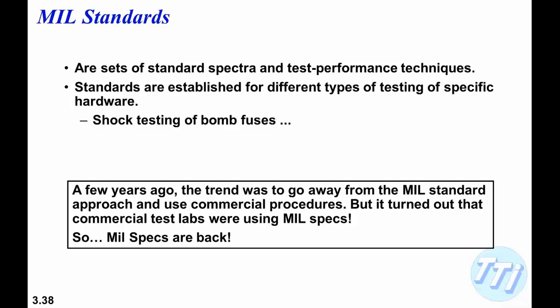Okay, just briefly, where do specifications come from? If we don't have a clue of what we're doing, what are we going to use for our standard spectra or standard time histories, or whatever you want to call it? The MIL standards are a set of standard spectra and test performance techniques, and they're established for a variety of different kinds of tests on specific hardware, like shock testing of bomb fuses and that sort of thing.